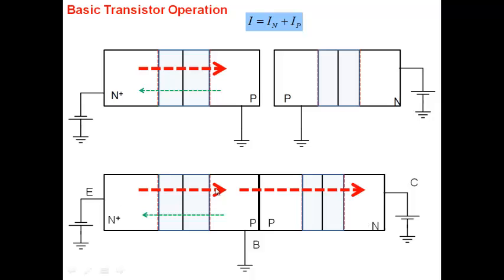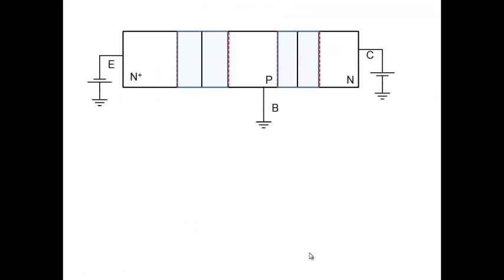Note, electrons injected here, the electrons flow across. Holes are injected from P to the N plus. That's it. Under this bias condition, this is the nature of current flow. Alright? So, straight flow of electrons all the way, it comes to the base and goes all the way to the collector and N plus here.